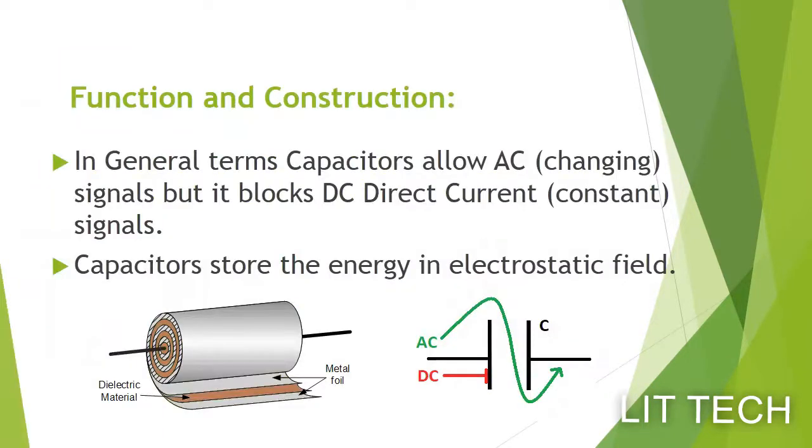Capacitor is a simple two-terminal device. Terminals are metallic plates and there is a dielectric material, such as mica, paper, glass, etc., which are insulators between them. Whenever voltage is applied across its terminals, also known as charging of a capacitor, currents start to flow and continue to travel until the voltage across both the negative and positive, anode and cathode, plates become equal to the voltage of the source, the applied voltage.